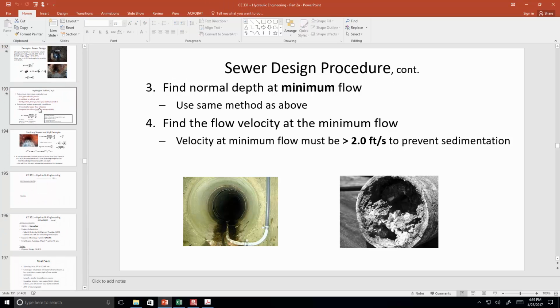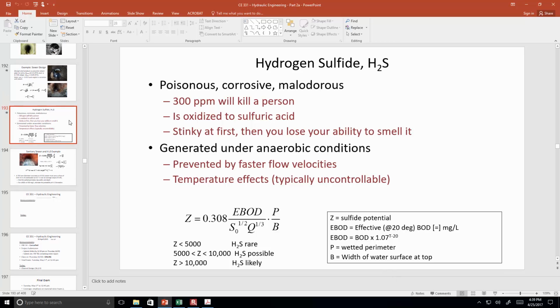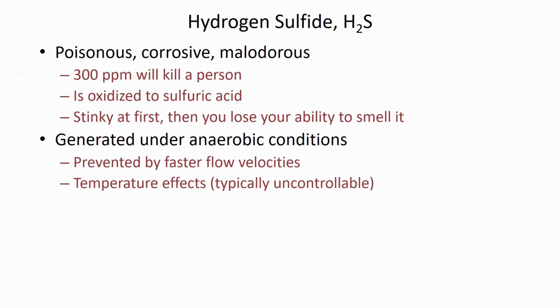All right. One last thing we're going to talk about today is hydrogen sulfide. It's a dangerous gas that can actually cause people to die. And it does. Every year, people die of hydrogen sulfide. If you've ever driven by people doing sewer maintenance, look carefully next time. If they're doing things right, they're really cautious. The guy who's going down will have a tether on him. They'll have a hydrogen sulfide detector. There's someone at the surface ready to pull the guy out if he becomes unresponsive because of this gas.